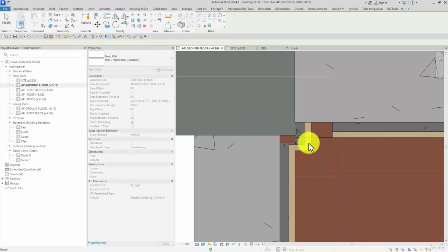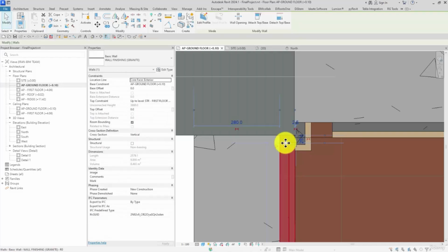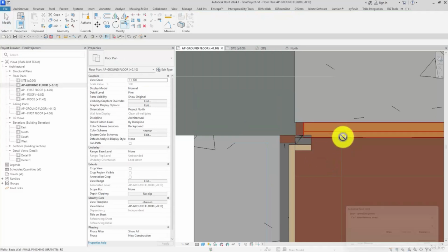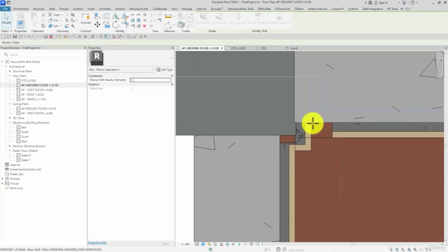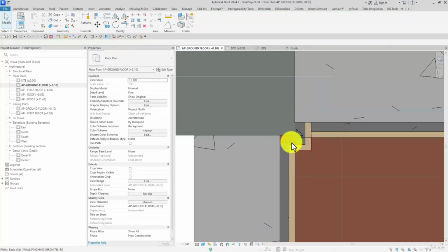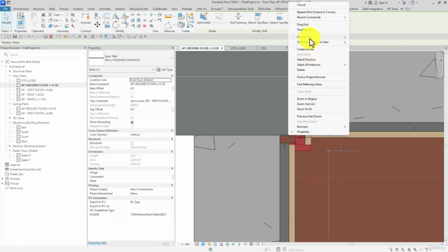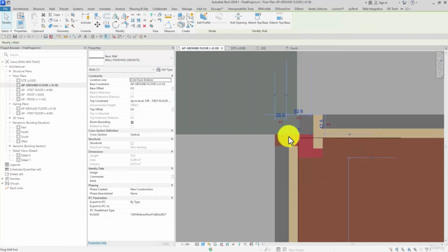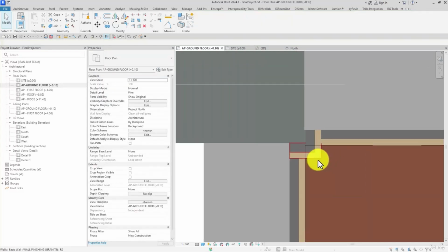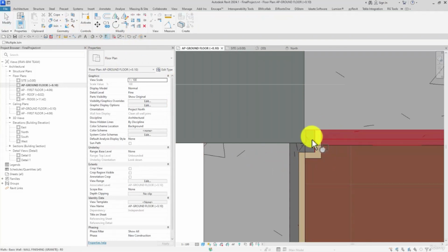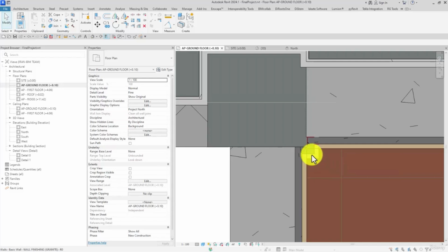Then we should fill the gap between the walls patiently in order to resolve the challenge. Look, and if I move this, then I disallow join, moving it upwards, and I select manually join, and I join them with each other. I select sweep join, like this way, and I fixed it.